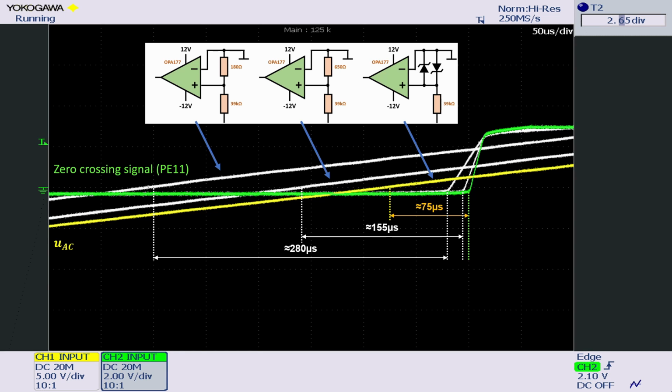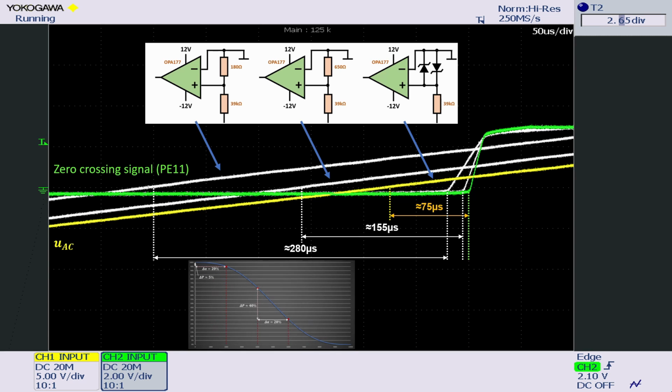However, as earlier discussed, a delta of alpha of 2 milliseconds could cause a delta of normalized power of up to 40%. As a result, an error of approximately 75 microseconds could cause an error of normalized output power of up to 1.5%. This clearly shows that our test setup will not exceed a much higher accuracy than 1.5%.